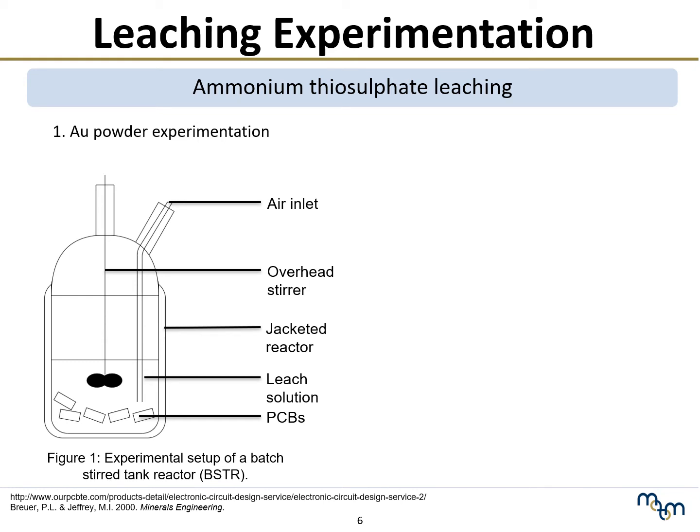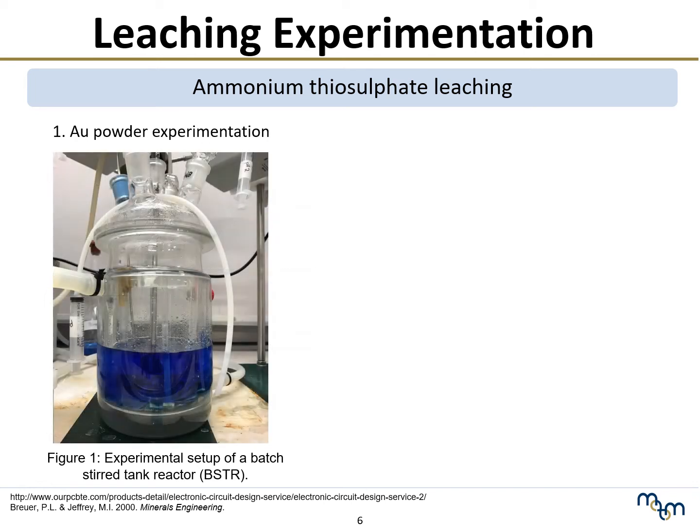These tests serve to validate the leaching chemistry and, more importantly, to generate pure solutions which can be used to test the ion exchange without the influence of contaminants, as well as to monitor the effect of background copper concentration on both the gold dissolution and the ion exchange process. Leach tests are then run on the actual standard PCBs, and leach solutions are analyzed to track dissolved metal concentrations.